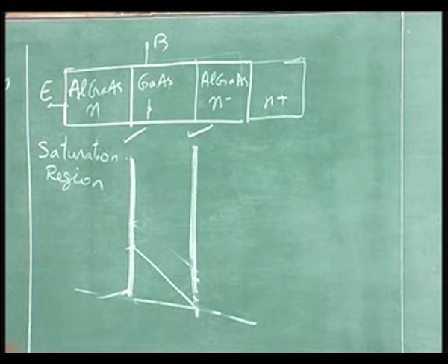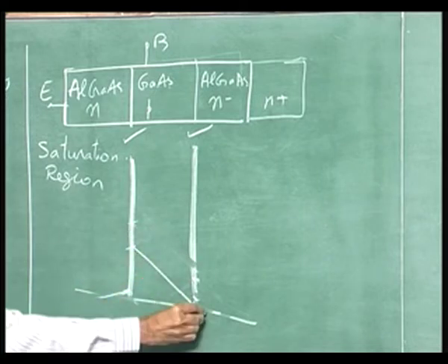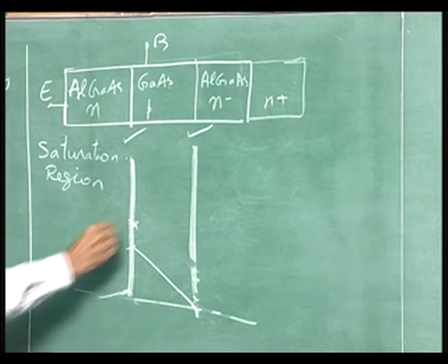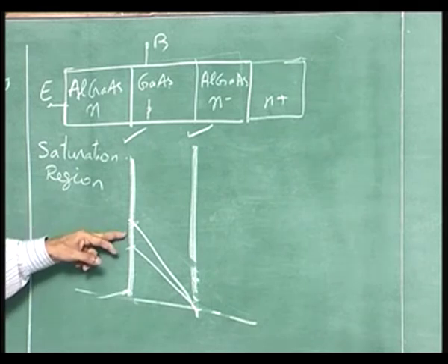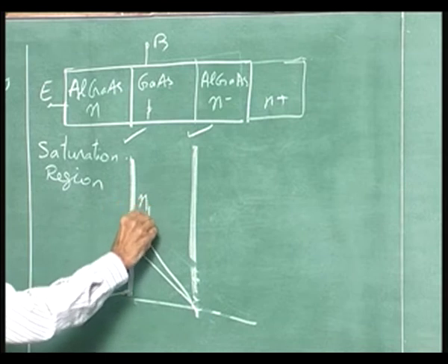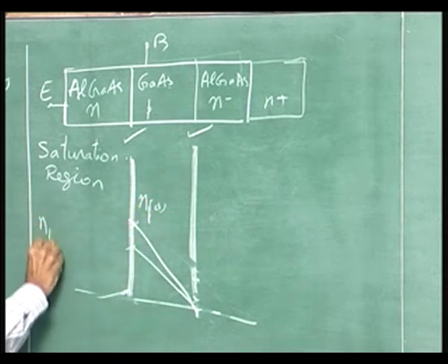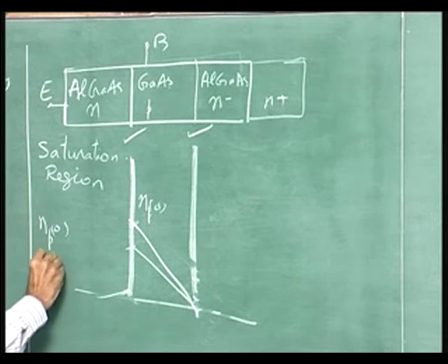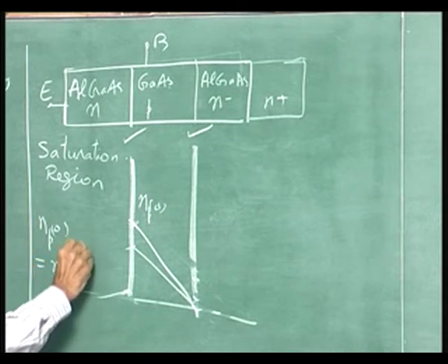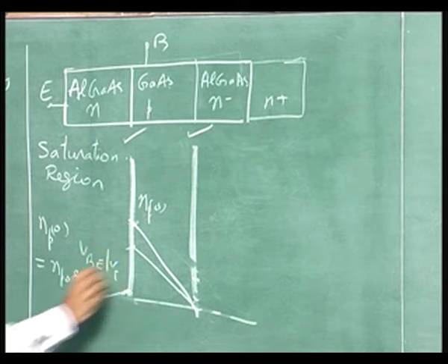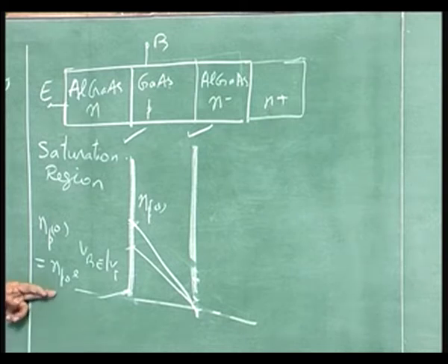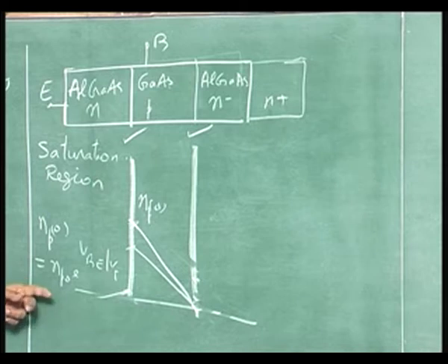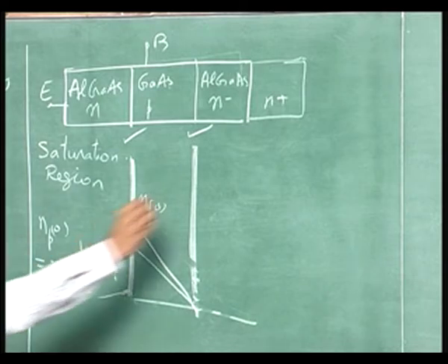Okay. How do you do that in this diagram? This is fixed, that goes up, and it is like that for the same voltage, because after all, np0 is equal to np naught e to the power of Vb by Vt, and np naught is actually the minority carrier concentration at thermal equilibrium. Okay. For a given doping, when Ni squared is larger, this will be larger, that is why that is larger. The minority carrier concentration np0 is larger if the band gap is smaller.